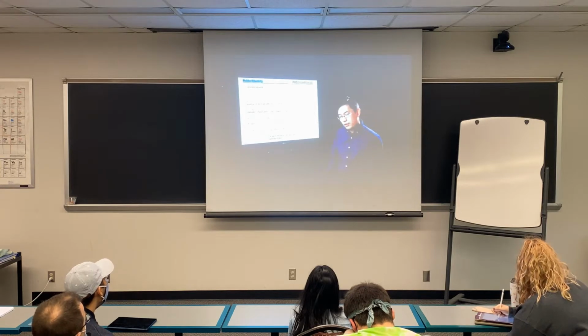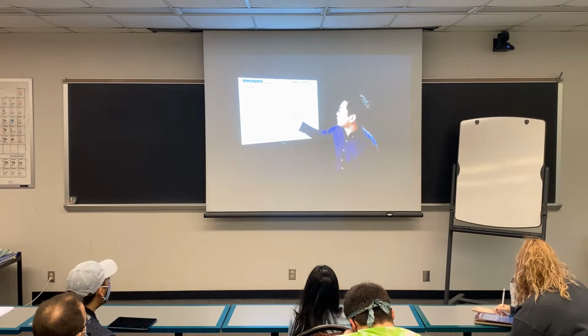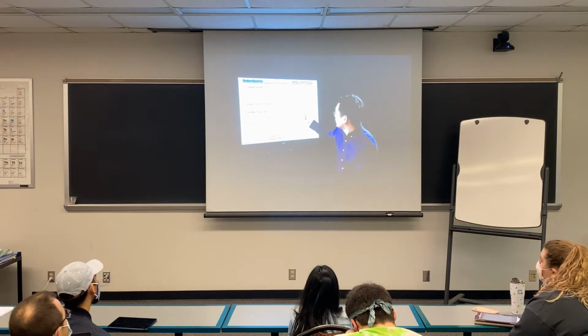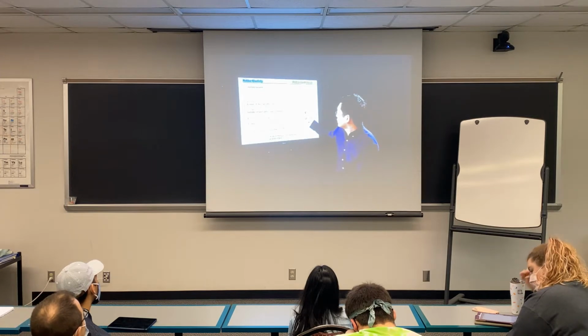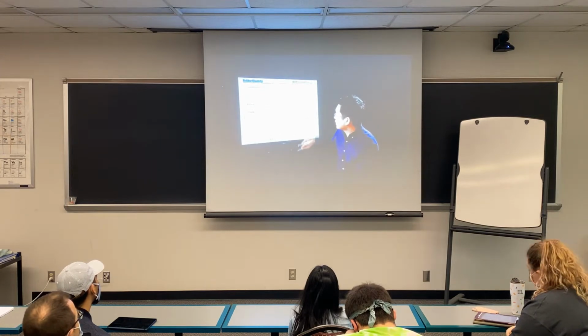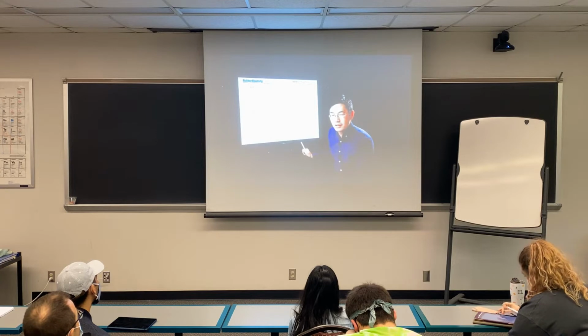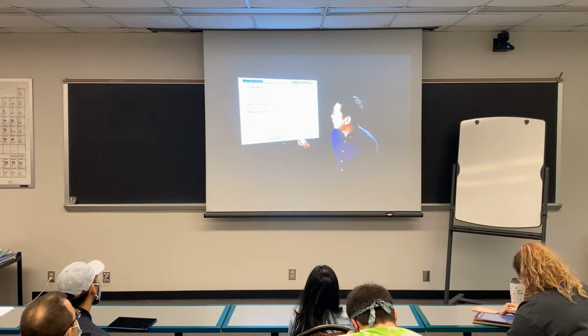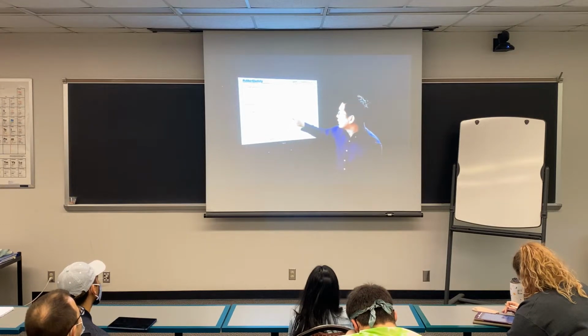There's one more modification we need to make. The effective strain on that network is given by rho times the Avogadro constant, divided by Mx, where Mx is the crosslink molecular weight between the crosslink points. We also need to consider defects in the crosslinks and trapped entanglements between the polymer chains.